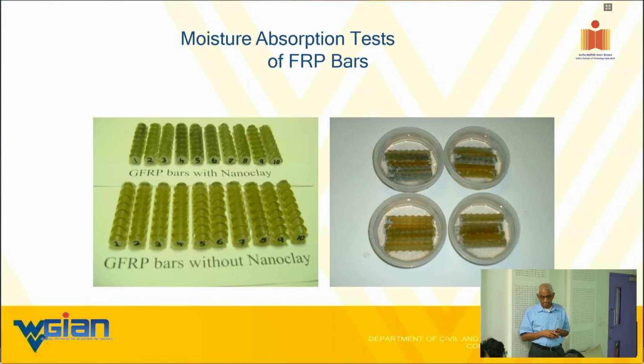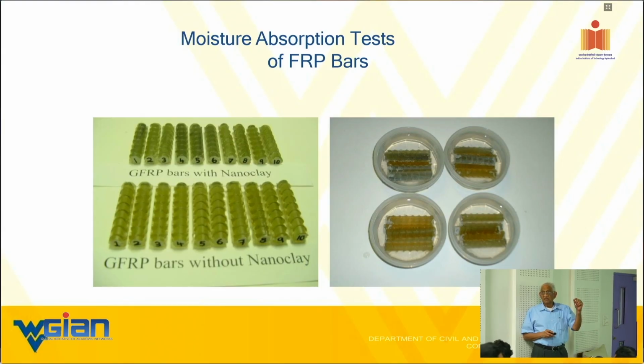So what are the changes which happen when we add these materials? Two things. Stiffness increases because I'm replacing 10-12%. Resin stiffness is lower than that of the clay. More important than the stiffness increase, which is nominal, permeability decreases. That is the key. It's the permeability issue that we are always struggling with.